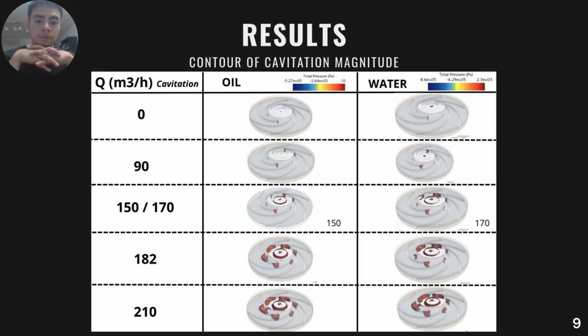For mineral oil, vapor pressure is close to zero. The results show some pressure values significantly below zero. Negative absolute pressure is not possible. These values are likely numerical errors in the simulation caused by things such as poor quality cells in regions with strong flow gradients, convergence errors in the pressure calculation, and solver pressure limits when pressure values are very close to zero.